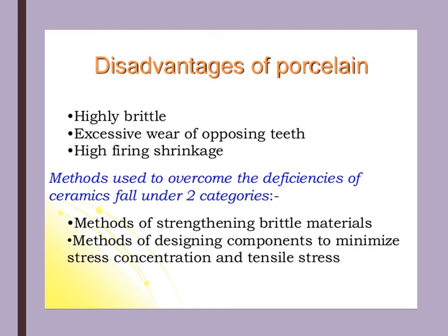Let's look at the types of strengthening, or basically the mechanism of strengthening. The residual compressive stresses can be generated by ion exchange, which we mentioned, the salt bath, thermal tempering, thermal compatibility. We'll discuss both of these in detail. As you can see from the picture below, in the process of ion exchange, the large potassium ions are moving into the place of the sodium ions, and this is generating a residual compressive stress. Then the interruption of crack propagation. So we are actually manipulating the intrinsic or the crystalline structure. So addition of a dispersion phase.